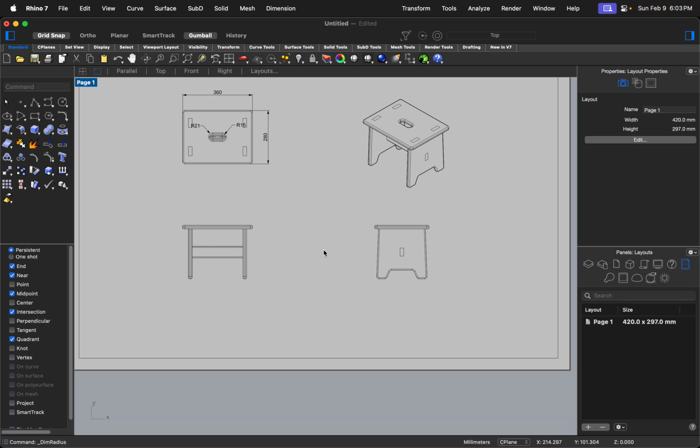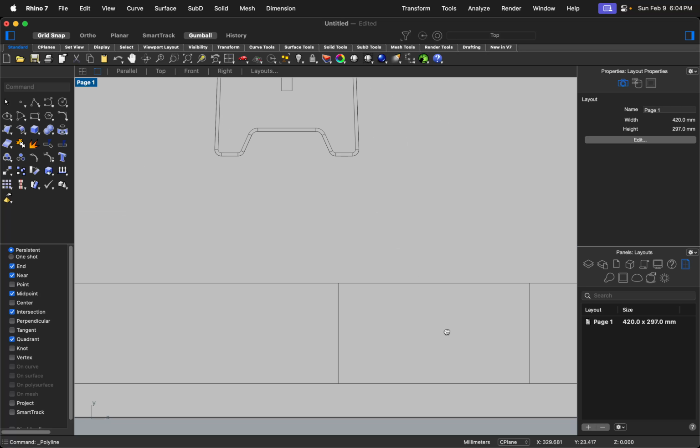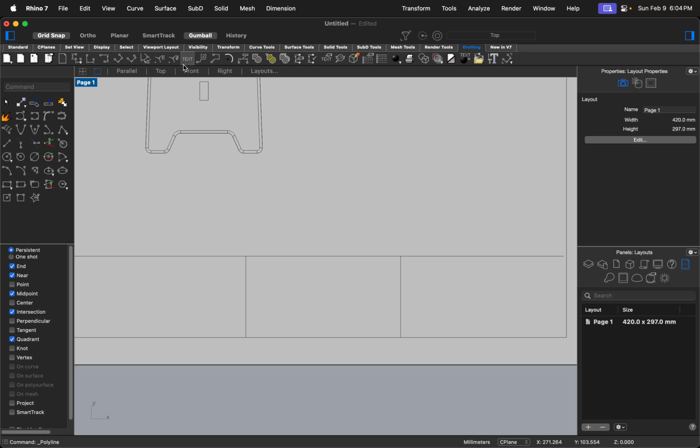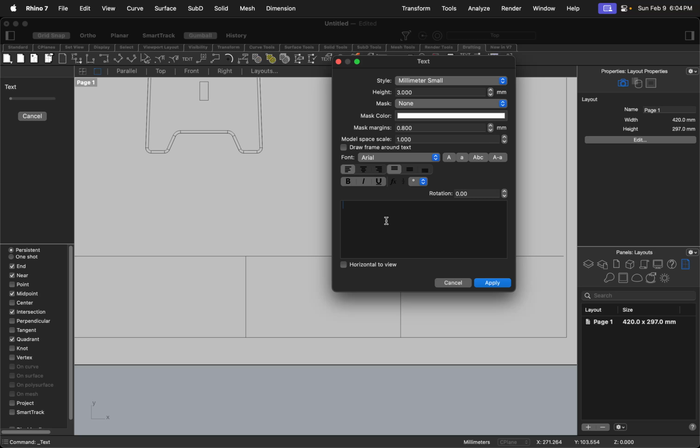And remember, the last one will be dropping out the label box here. And that we can just simply do with the line. For example, I just draw some lines across. And then I can draw different boxes. Like for example, if I'm happy with here, I can then use the dropping tools to put in the text. The text I will put here, like text, for example, scale